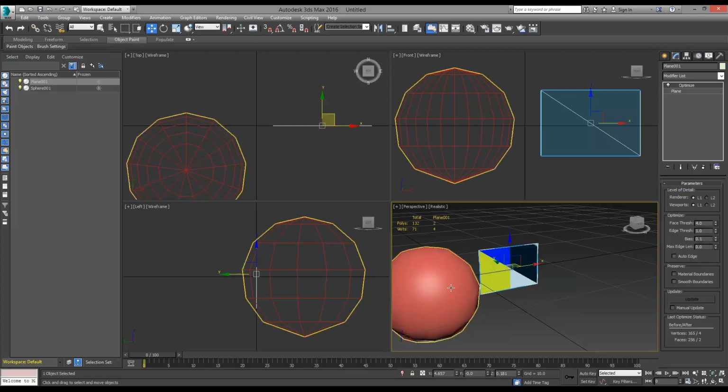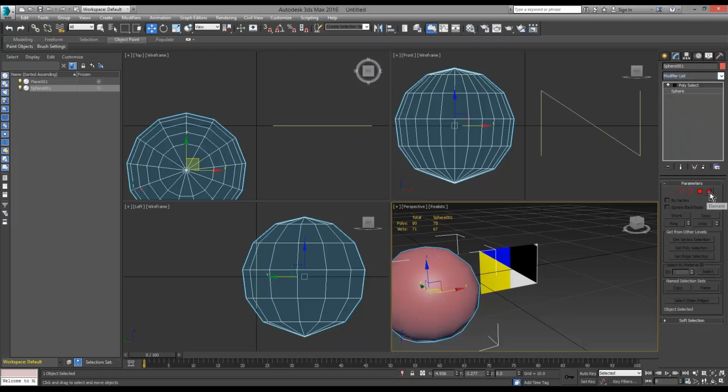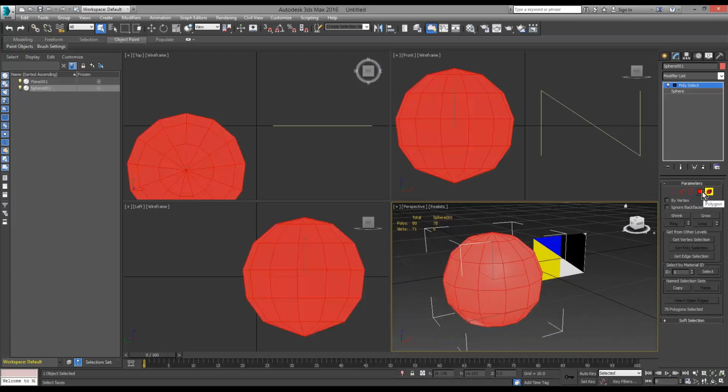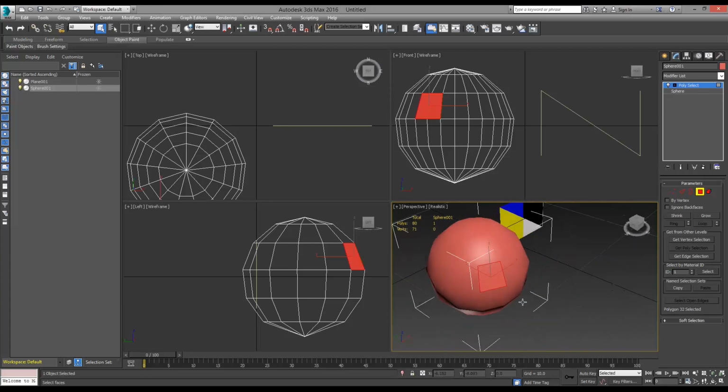Vertex and polygon. Let's have a look in here, and I want to show you the, was it polyselect? Yeah. With this button here, you see that I'm selecting the entire object. With that button, here they call it again polygon, I would call it actually face, you can select each face separately. Now here it's important to know that this is again separated into triangles. So indeed there are actually 2, but you can't select them right now with this tool. And then the vertex is actually this one.